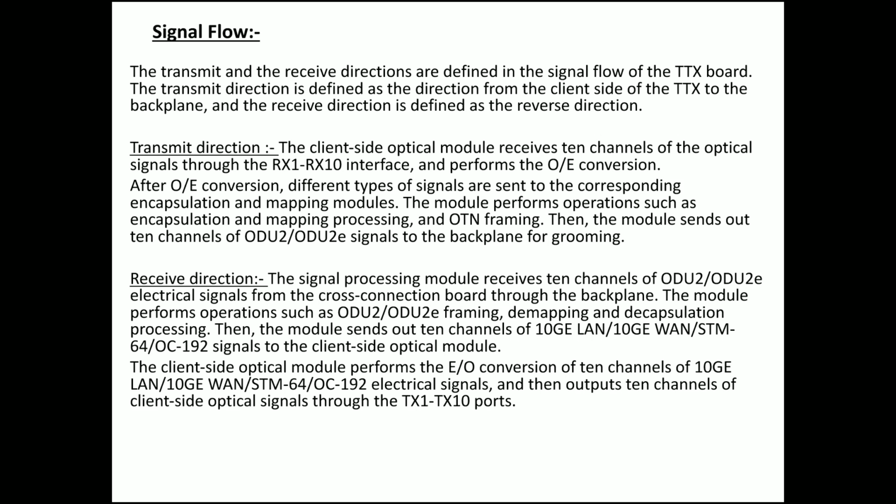So here is the signal flow. The transmit and the receive direction are defined in the signal flow of the TTX board. The transmit direction, it is very important. The transmit direction is defined as the direction from the client side of the TTX to the backplane, and the receive direction is defined as the reverse direction.